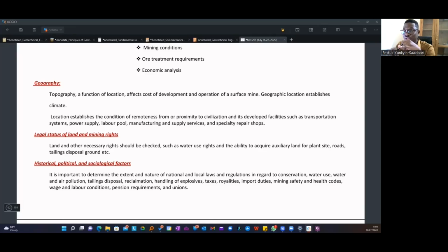And once there are hills all over, the possibility of having river bodies around that area will also be high, which means if I want to mine, I will have to strip certain materials. If the deposit is hiding below a hill, it means that the whole of that hill becomes overburden material I have to struggle to take out.